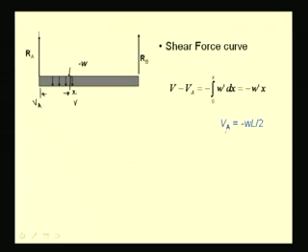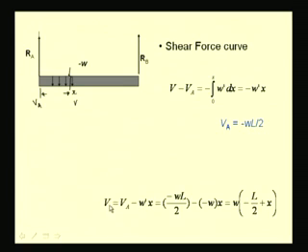We can find that the shear force at A is minus WL by 2, and so the shear force at any section is equal to W times of minus L by 2 plus x.